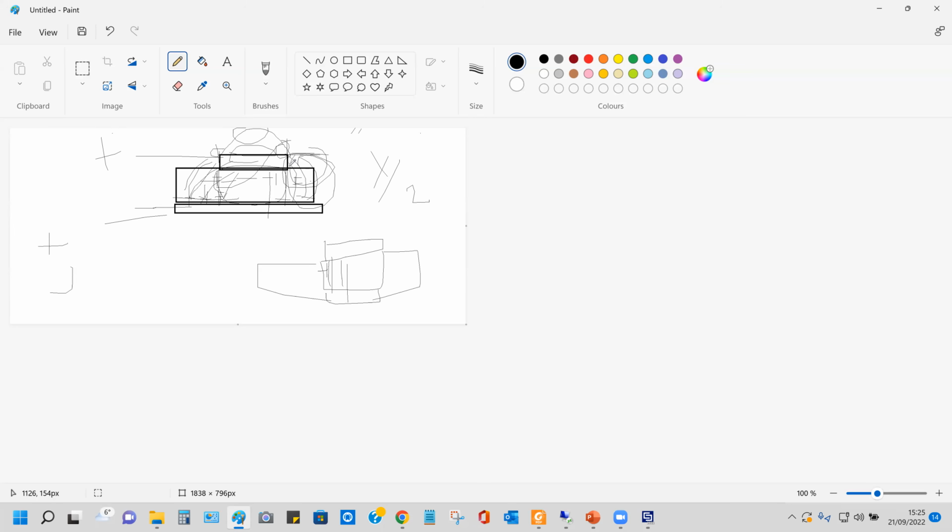So the point I want to make is, in the patch antenna formula you might have seen, epsilon r effective is equal to epsilon r plus 1 divided by 2, plus some value, 1 by 2 of 1 plus w by h, like that. Why do they put it like this?